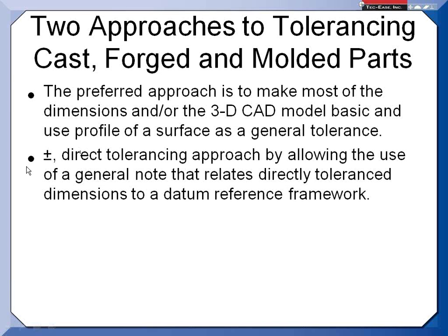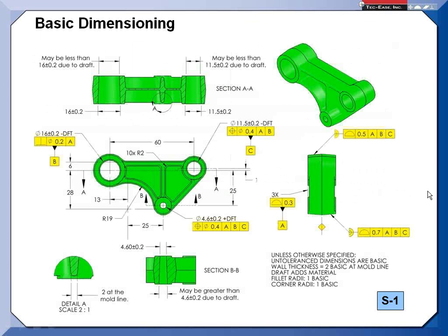So it's still there. We talk about it in 14.8, but I did survey the casting committee about a year ago, and several of the people there make castings and forgings, molded parts. And I said, what % of you folks are working off the 3D CAD model? Of the work that comes in, what % is really using the 3D CAD model? And they estimated about 85%. So you can see that this plus-minus approach, although it's covered and actually sort of featured just as legacy, hopefully will be going away.